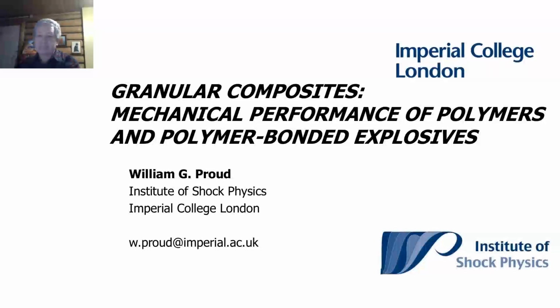Okay. So what we've tended to find, and this links to one of the talks next week, is in terms of the impact interface. If you've got a polymer bonded system, then the outer part of that system tends to be predominantly polymer. So it's mainly polymer in contact with the impacting plate, or with the container, because the grains tend to be dipped into it. So you've got this polymer rich layer, which also means, because it's on the surface, you can have a greater presence of things like voids.